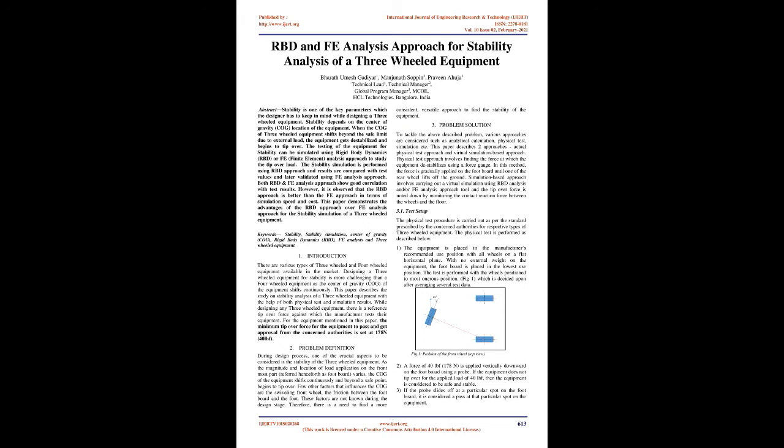When the COG of three-wheeled equipment shifts beyond a safe limit due to external load, the equipment gets destabilized and begins to tip over. The testing of the equipment for stability can be simulated using rigid body dynamics, RBD, or FE, finite element, analysis approach to study the tip-over load.